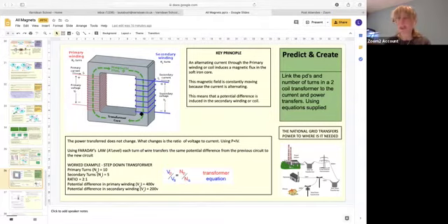That's not going to set up a current here. It can't. Remember, because you've got to have some movement. So if I put through an alternating current here that is going backwards and forwards, I'm getting this flux here as well. And so this flux here can then induce potential in this wire.